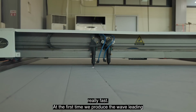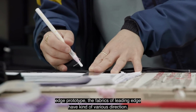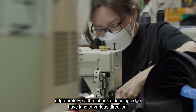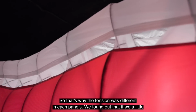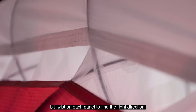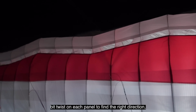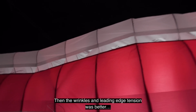The first time we produced the very leading edge prototype, the fabric of the leading edge had a kind of bias direction, so the tension was different in each panel. We found out that if we twist each panel a little bit to find the right direction, then the wrinkles and leading edge tension were better.